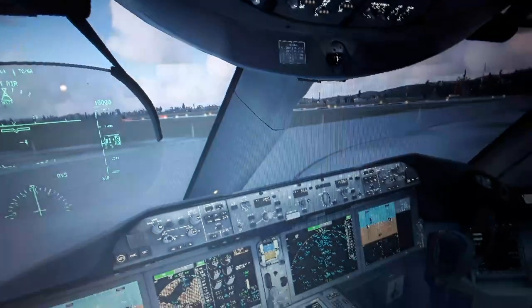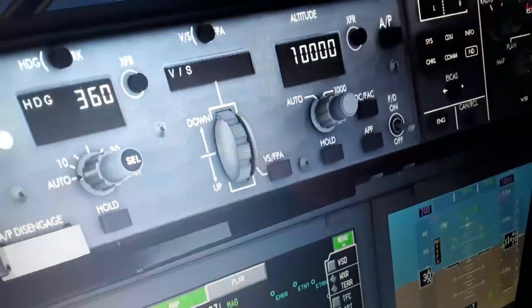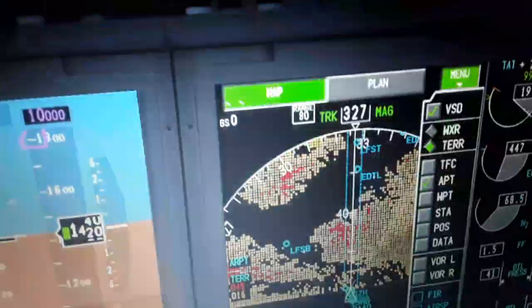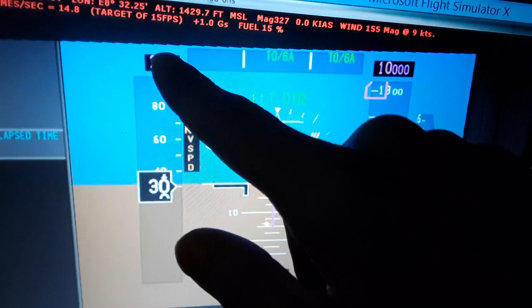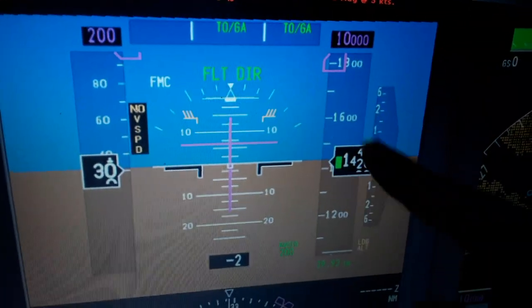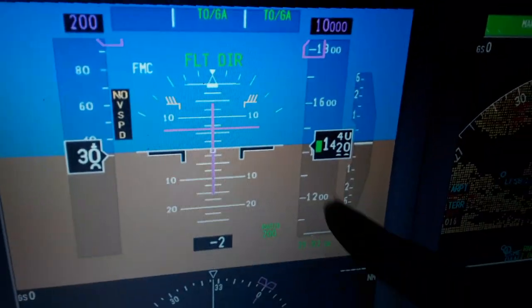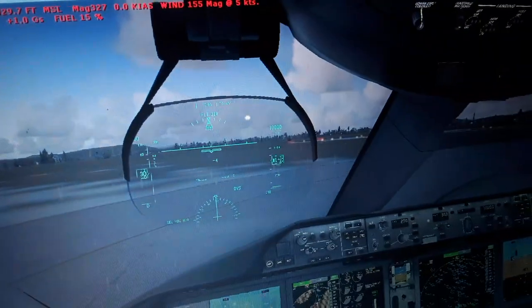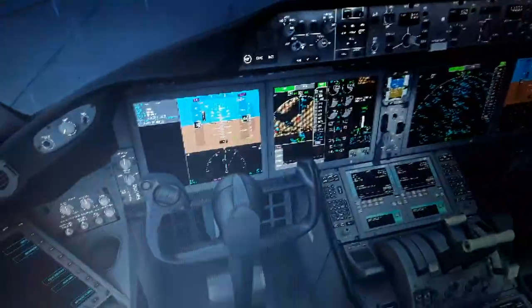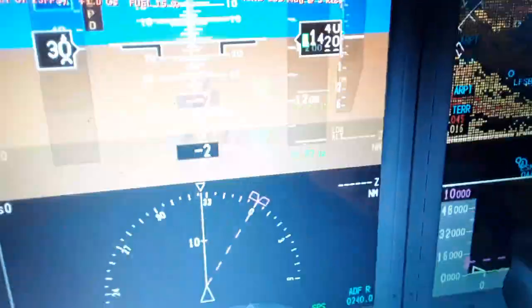The displays, autopilot flight director system panel over here. You're gonna see the display, primary flight display. You can see here we have the airspeed tape, the indicated airspeed, airspeed selected from the autopilot flight director system panel, barometric altitude above sea level, barometric pressure of the outside atmosphere. So we need to set the barometric pressure altitude over here to have the correct altitude reading as we fly.